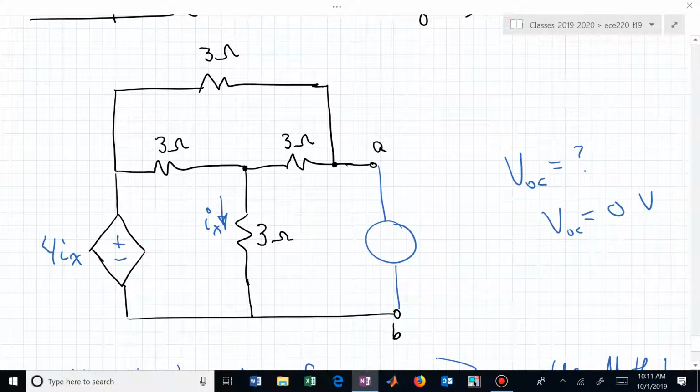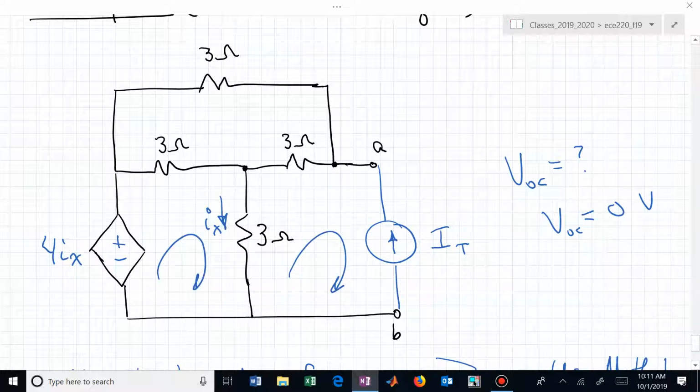If you used a current source, so here's our thought process. If we said, okay, here's a current source, well, that's kind of begging us to do mesh analysis. If we see 3 window panes or 3 meshes, now this particular mesh is given. And we have 2 unknown variables to solve, mesh 1 and mesh 2. Correct?